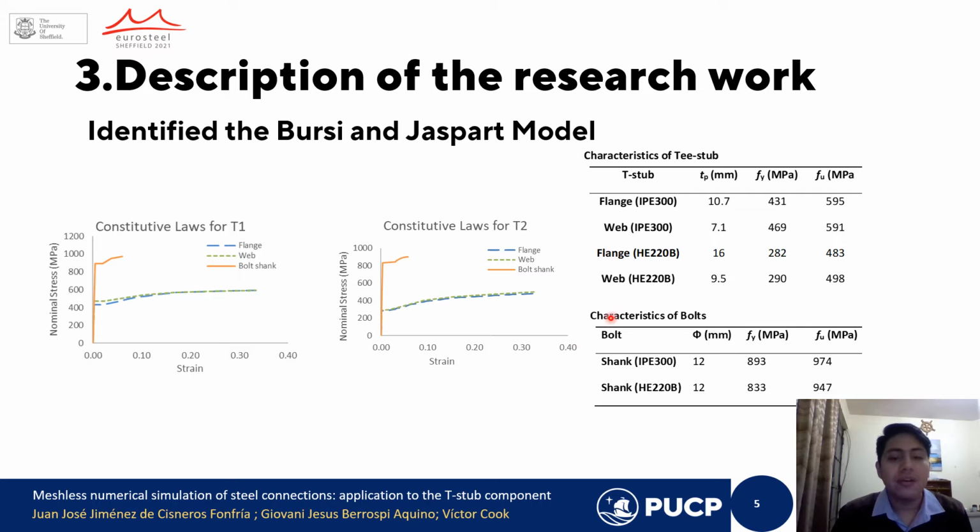Then we can find in the work of Jasper and Berrospi the constitutive law of the T-stub T1 and T-stub T2. This is a piecewise linear stress-strain curve, and we employ this curve in SimSolid. This curve is the engineering curve, not the true one, because SimSolid requires the engineering curve. And this is different to the FEM model. Well, the FEM model requires the true stress-strain curve.